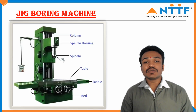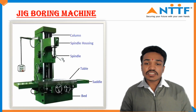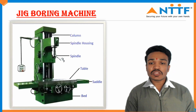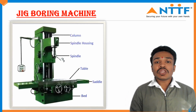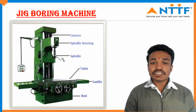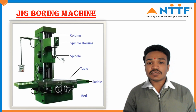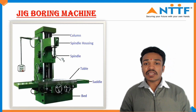This is the picture of a jig boring machine. There is a bed. The bed is made of rigid material, and the saddle is mounted on the bed. The table is mounted on the saddle. The column is at the backside of the machine. On the column, the spindle housing is mounted, and the spindle is mounted on the spindle housing. The spindle housing is movable in the z-axis through the column.